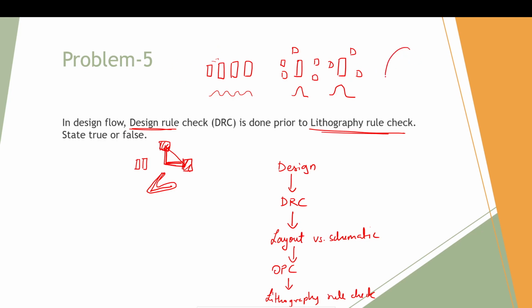Whenever you are doing lithography, there will be multiple reticles. In each reticle, if there are some places of high density and some of low density, because you are exposing the entire thing with the same exposure dose, it will create problems. So it's better to have everything at the same pattern density. To make sure of that, we add some dummy structures, some cross or a series of boxes. They won't affect the device performance, they are just there to fill the layer.